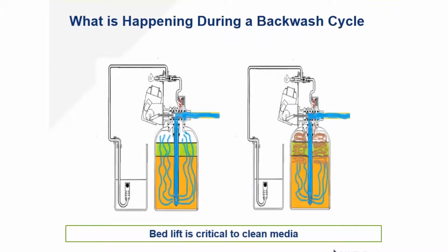What this does for us is it causes the bed to lift and allow for a scrubbing action from the turbulent, chaotic motion of the media, whether that's water softening resin or activated carbon, whatever it is. You need to get this bed lift. And bed lift and expansion is predicated upon the media itself. Okay, we'll get into the technical details of that later.